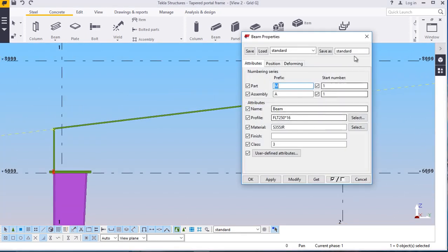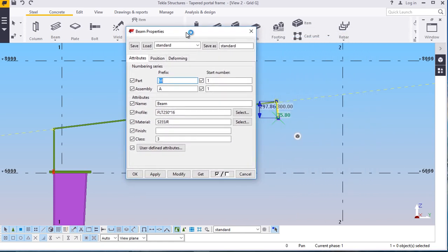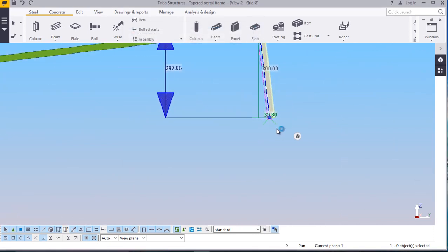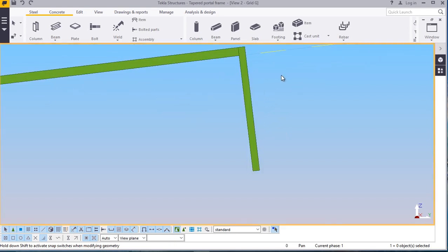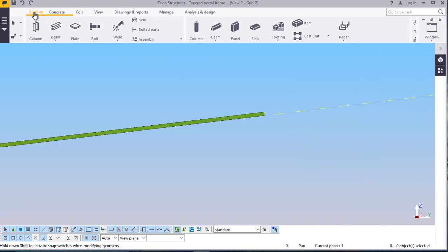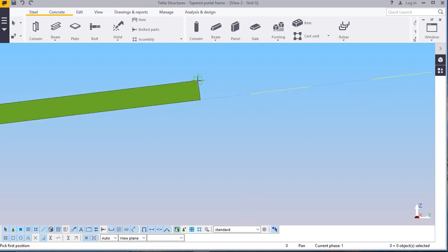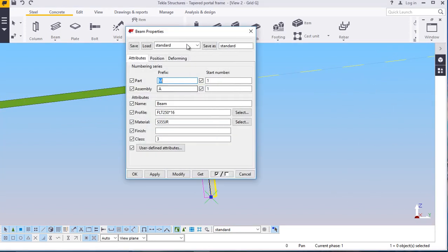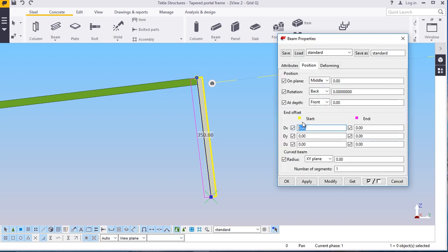Double click on this. It should be slightly bigger. Delete that. Come to steel again, steel beam, click and place your cursor down there and type 350. Thickness, check by double clicking, is now 16. Double click on this and extend. Come to that, -50, and 50.